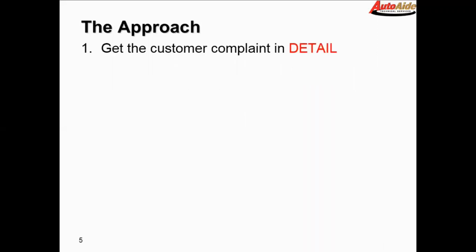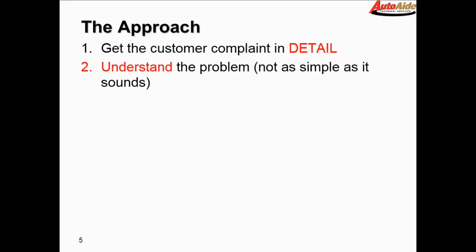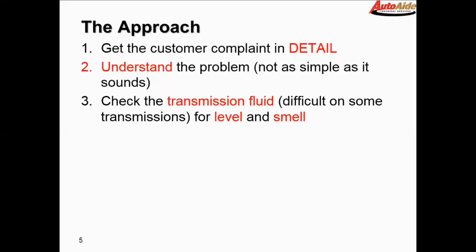So the approach is always to get the customer complaint in detail. In a lot of cases, that may require you to road test the vehicle with the customer, especially if it's not obvious what the guy's complaining about. Then, once you understand what the customer's after, you do have to take some time to understand the problem that you're faced with. I know that sounds simple to say, but it can be quite a bit different when you get in there, so it's not as simple as it sounds. And I always stress when it comes to transmissions, check the transmission fluid.